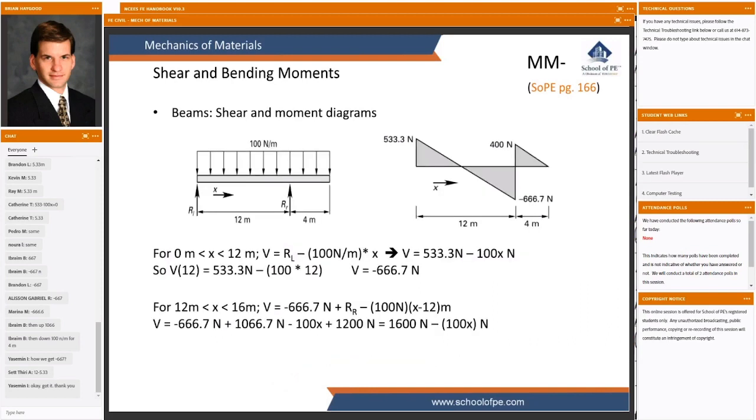So there's our shear diagram. Now, if somebody asked you to calculate the stress caused by shear, you might not be interested in what's happening at the 3-meter mark or the 5-meter mark, but you know that the worst shear stress anywhere is this magnitude. So that 667 seems to be sort of a key point, and we might take that shear value V, and in a few minutes we're going to learn how to turn that value of V into a value of tau. But at least we know now where on the beam to look, where we think a failure might occur due to shear.